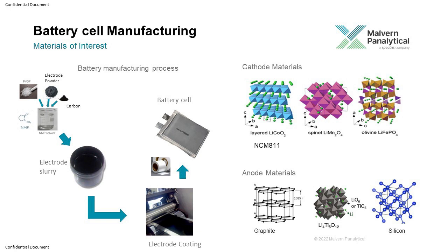So if you are using this as the anode, you have the better lifetime, faster charging, and more safe batteries. But there is a cost that energy density is lower. So where you don't require high energy density, then this material has a lot of advantage. And for example, Toshiba has, I think, patents on this technology, and they promote this as the anode material.